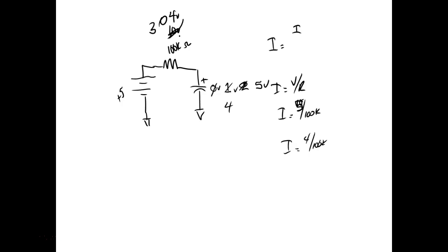And like I said, in this situation right here, we would probably be okay because we're protecting it with a 100K ohm resistor. In power supplies, guys, we are not protecting this guy at all. The only resistance in the circuit is the resistance of the transformer. So in a power supply, the capacitor charges almost instantly. It charges with the sine wave. With the pulse.